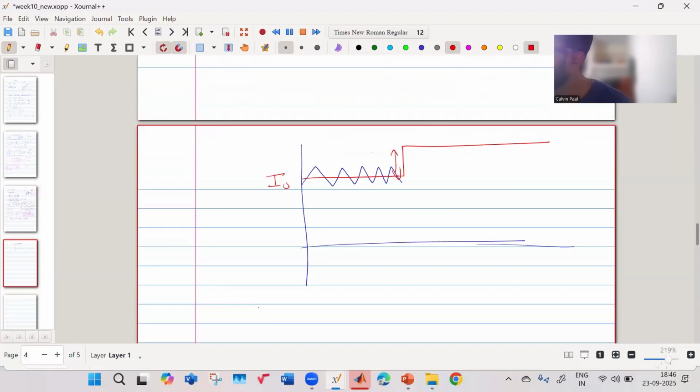So there's a step change of your load current, that is going to be a delta I naught. Now, previously your capacitor current was going same way, only it had zero average. Now, because your load current has changed instantaneously, your capacitor current will have a dip.